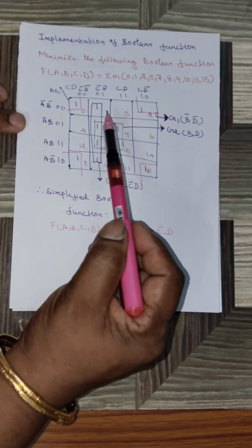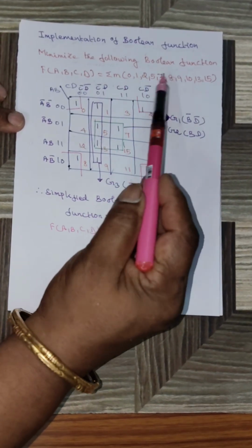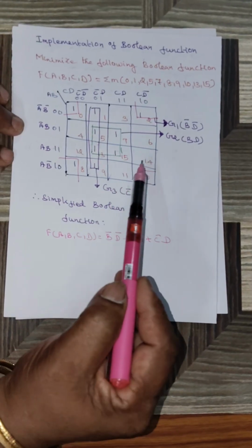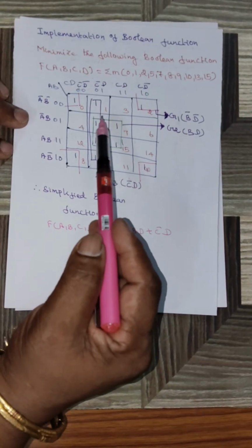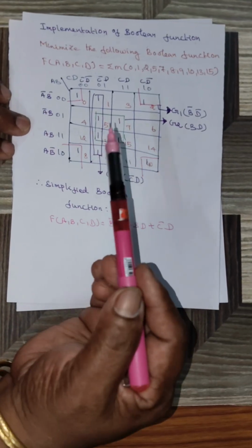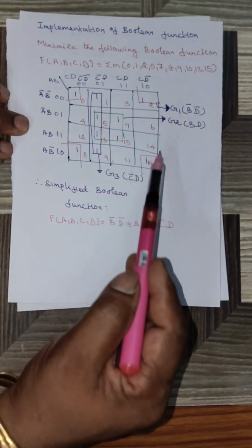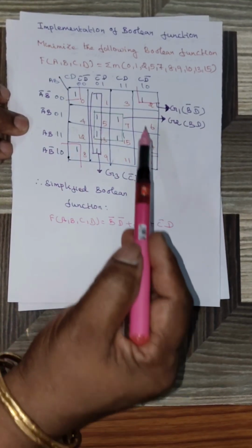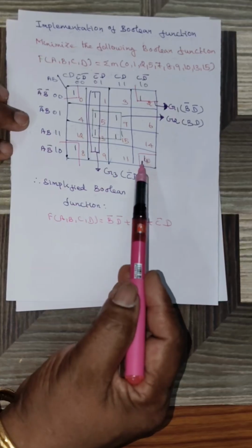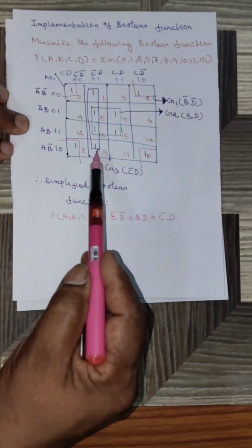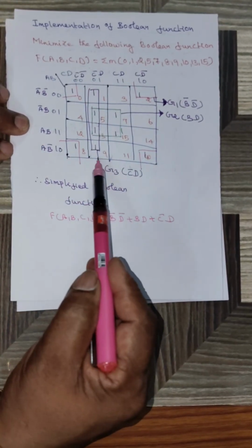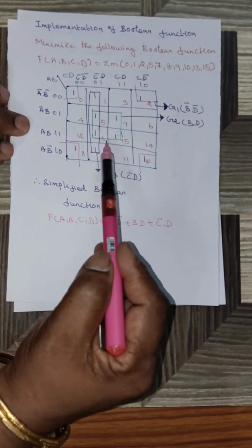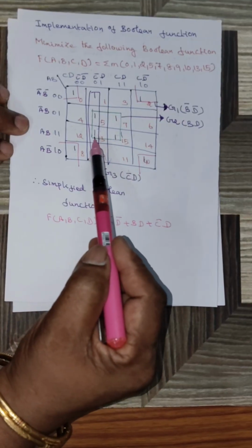Now we are going to plot the K-map. So here the given minterms are plotted as 1 and the remaining minterms are taken as 0. Then we have to group the given ones. You see here there are four ones at the corner of the K-map, so those 4 ones can be combined into a quad. Similarly these 4 ones are vertically adjacent to each other, so we can form a group here also. And these 4 ones form a square and we can form a third group here.